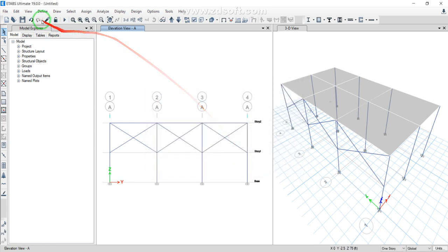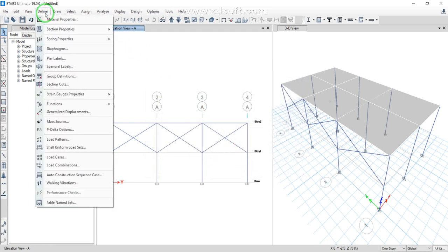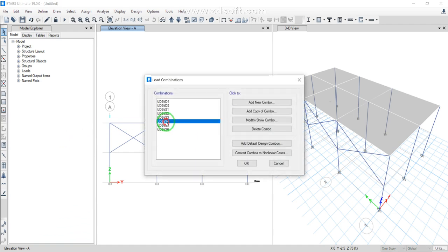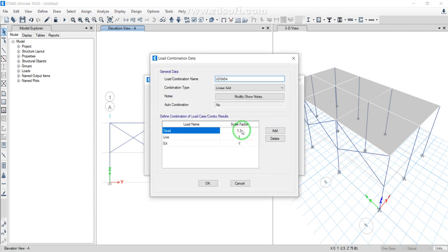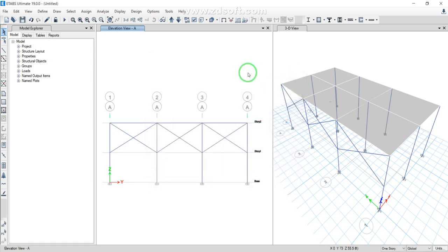After you have all of your load patterns, you need to go to this part at the end, before your analysis and before your design. You need to go here, update the information that you have, then come back and have your load combination when you use the automatic one. You can see that this 1.3 is because of the vertical seismic load, and it's dependent on the SDS, if you remember that. That's why I said that we have to define the SDS before we move forward.